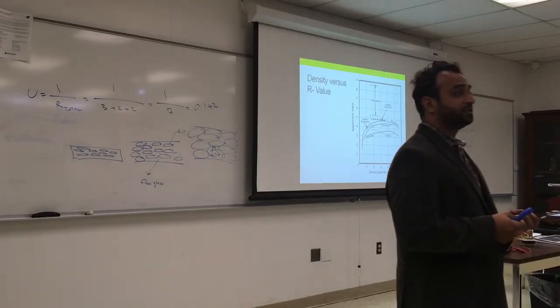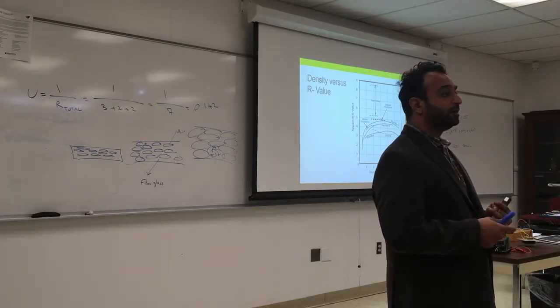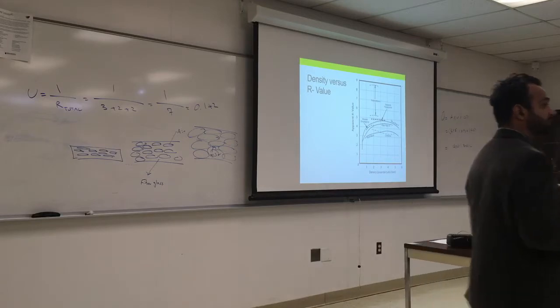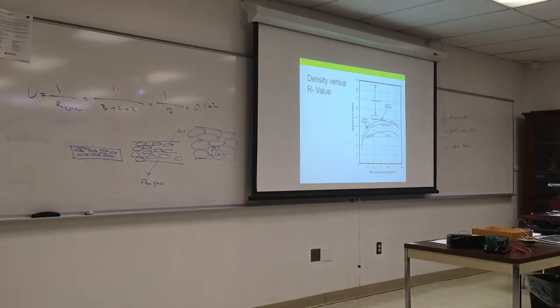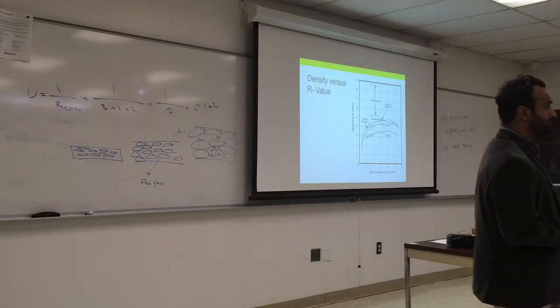What are other insulations? We talked about foam. Foams come in different shapes. Polyethylene. There's something called aerogel, which comes in sheets, like fabric sheets. It's around 1 or 2 millimeters, and it has really good insulation value.